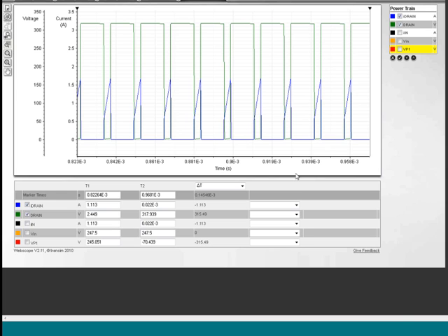There's a couple of other features in this tool. For example, I have these 2 little cursors that I can drag over. So I can come in here and measure between this point and this point, and I can see that between these 2 markers, I have a delta time of 14 microseconds. So it's 10 to the minus 3. If I switch this over, I can get the frequency, which is right at 67 kilohertz. And that shows me the delta time between those 2 markers, so I can see where those markers are.